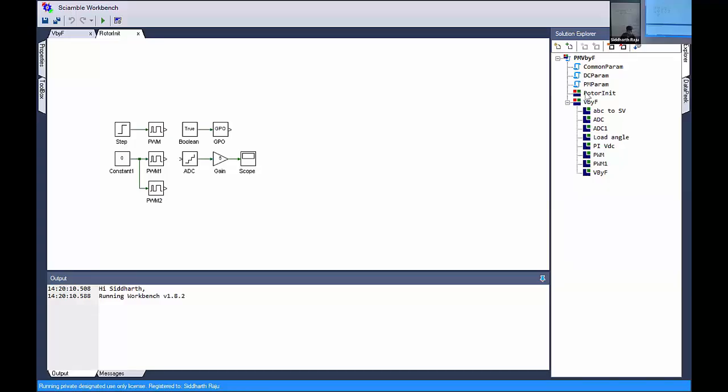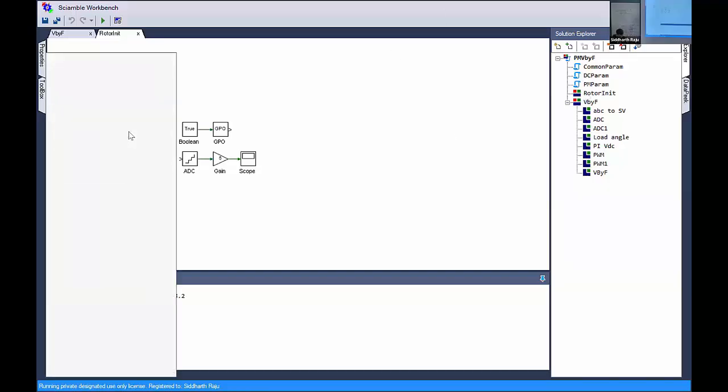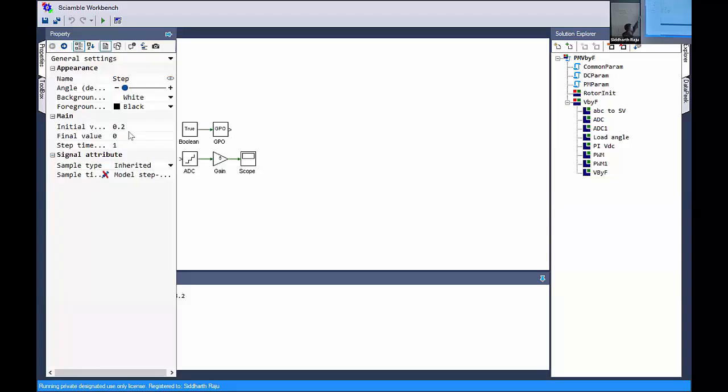So to do that, what we do is we initially give a small pulse voltage. We start the A phase with some voltage and then make the voltage 0. So if you pass current in the A phase and apply no voltage across the B and the C phase, what will be the direction at which the rotor magnet will align? So if there is a current going in the A phase coil and the B phase, C phase have no current, then what will be the direction in which the rotor would align? Along the A phase, because the rotor magnetic field is along the A phase axis.